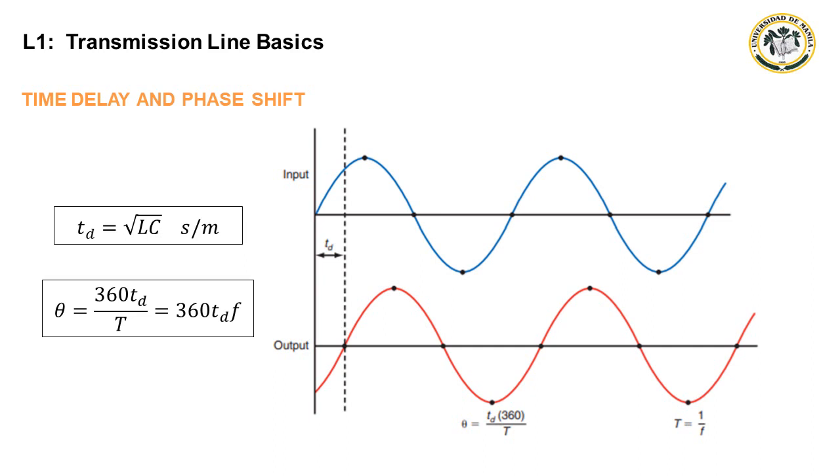Alternatively, a more compact distributed delay line can be constructed, consisting of a coil of insulated wire wound over a metallic form. The coil of wire provides the distributed inductance and at the same time acts as one plate of a distributed capacitor. The metallic form is the other plate. Such artificial delay lines are widely used in TV sets, oscilloscopes, radar units, and many other pieces of electronic equipment.